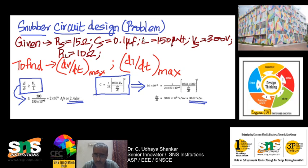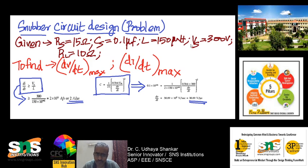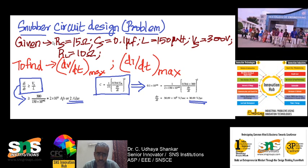So L will be used for di by dt protection, whereas RS and CS will be used for dV by dt protection. L is called a turn on Snubber, and RS and CS in combination, connected in parallel, is called a turn off Snubber. So RS and CS will be used during turn off conditions, whereas L will be used for turn on conditions, in order to limit the di by dt.